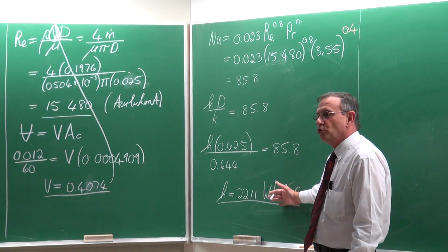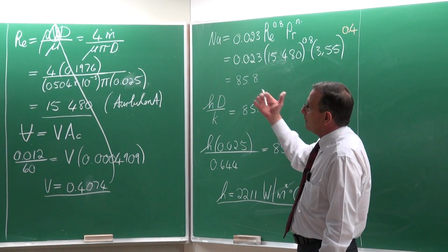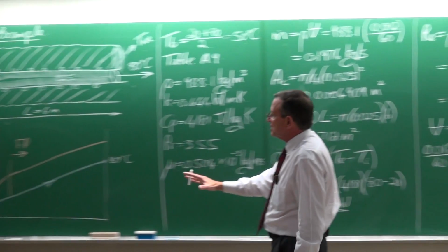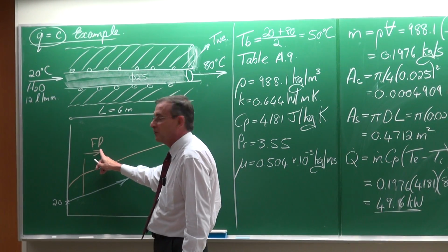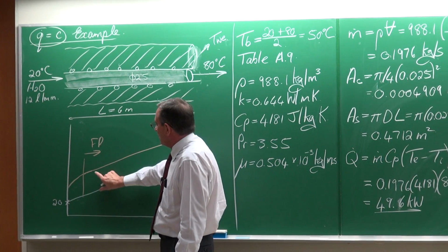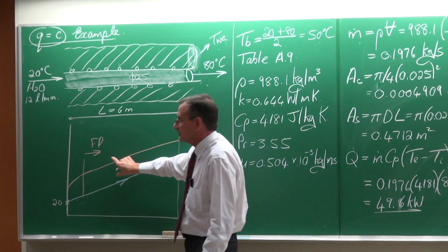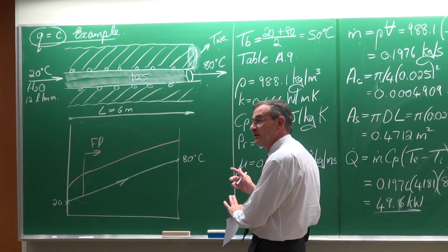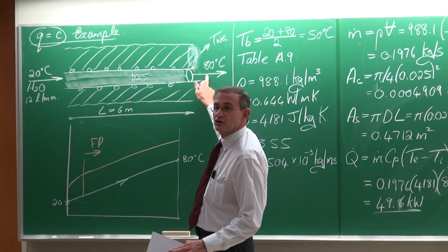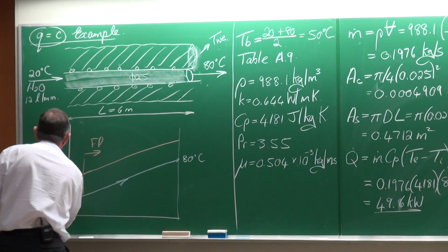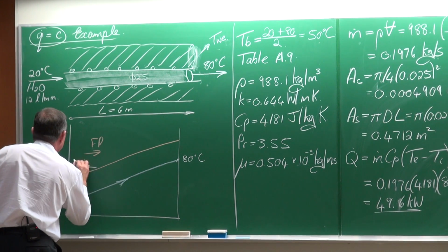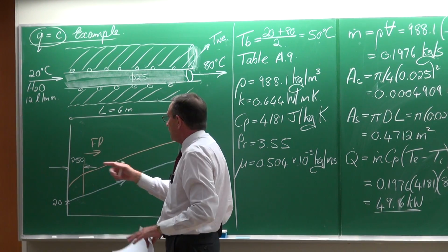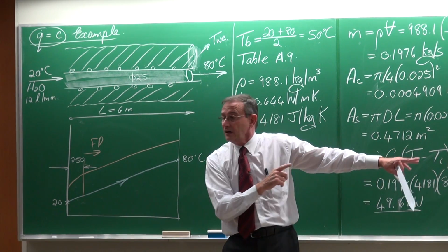It is always important to think about the flow regime and the heat transfer coefficients. So if we come back to the sketch that I've shown to you in terms of the fully developed part, in which the heat transfer coefficient will be constant. For turbulent flow, it takes 10 diameters before the flow is fully developed. 10 diameters is 250 millimeters. Okay. So that distance is 250 millimeters. So in that 250 millimeters, the heat transfer coefficient will be higher than that value that we've determined there.